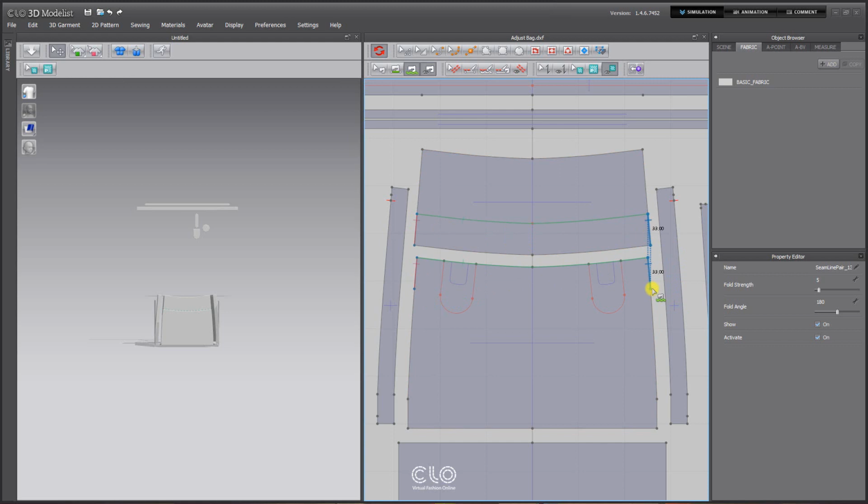Next, this long pattern will connect to 2 overlapping patterns. To connect these 2 patterns at once, use the one-to-end sewing function. First, establish the sewing line on the long pattern piece. Then, with the Shift key held down, create sewing lines on the sides of the 2 patterns, being mindful of the sewing order. Repeat this for the other side of the bag.